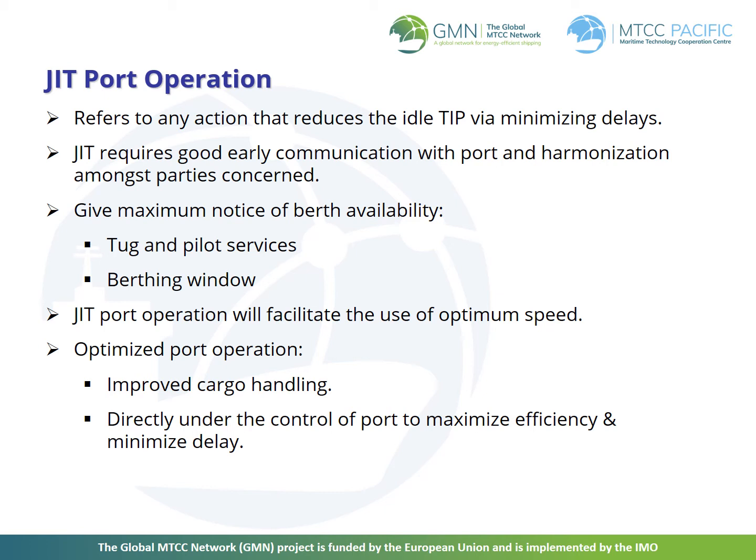According to the 2012 guidelines for the development of a Ship Energy Efficiency Management Plan, or SEEMP, good early communication with the next port of call should be an aim. This procedure allows for maximum notice of berth availability and facilitates the use of optimum speed where port operational procedures support this approach. Optimized port operation may involve changes in procedures depending on different handling arrangements in particular ports. Port authorities should be encouraged to maximize efficiency and minimize delay.